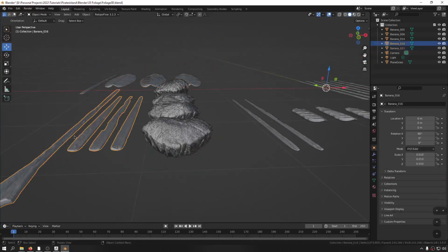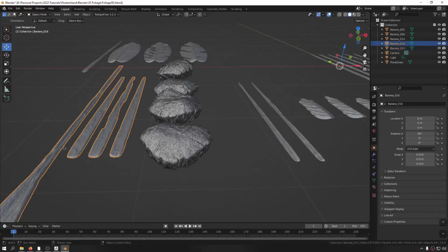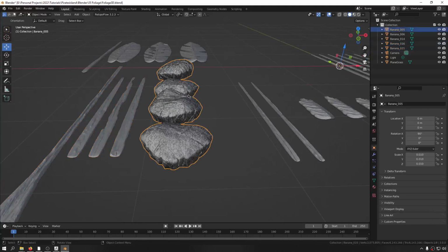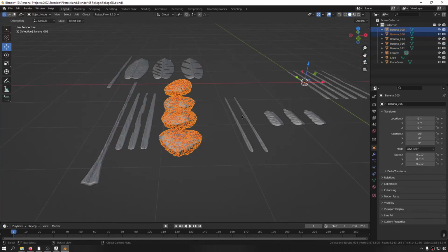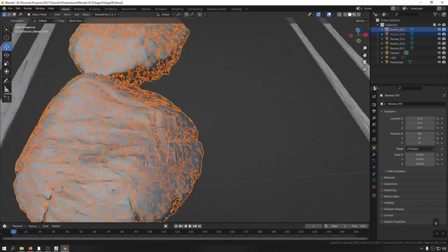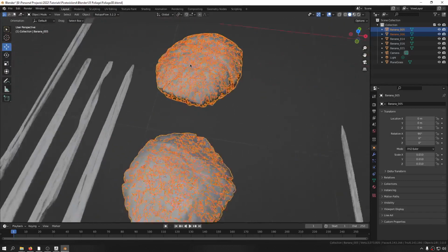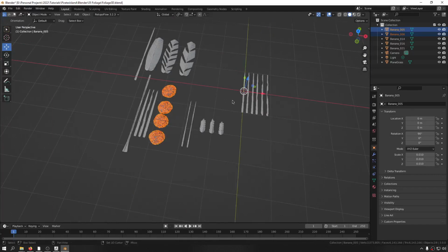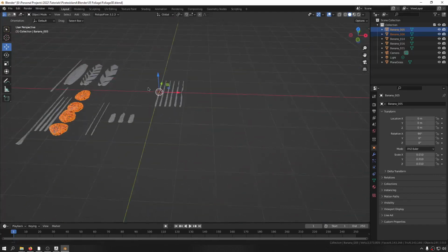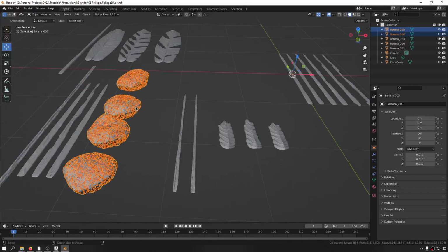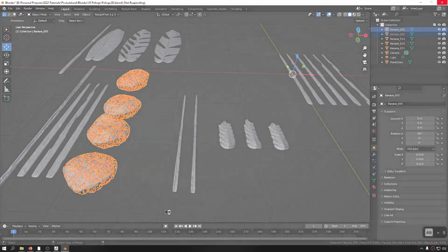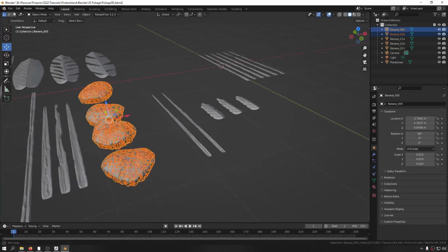And then the bark, leaves, and a stem, I'm going to make meshes with these and bake them into a single plane. But these ones are actual geometry, which I need to do using the old method of baking high poly into low poly. So I'm going to first take care of these and then go for other ones in here as well. So let's select them, Alt S to bring the pivot onto its place.